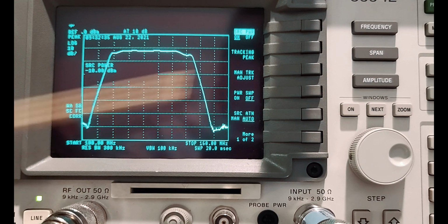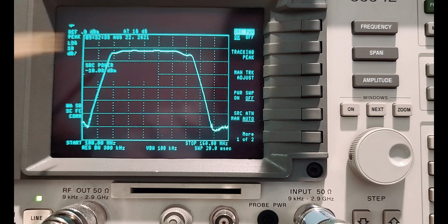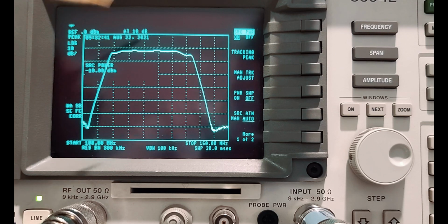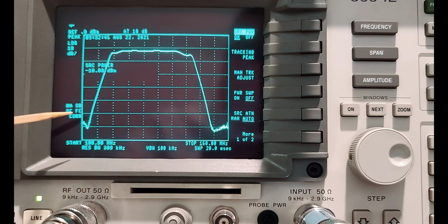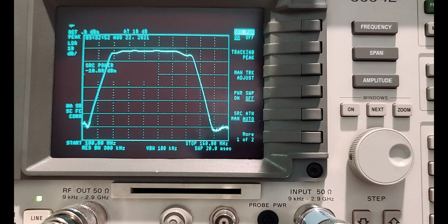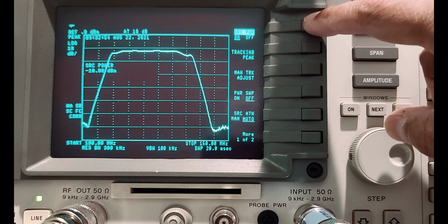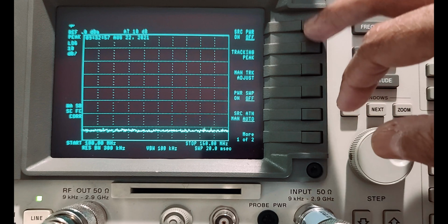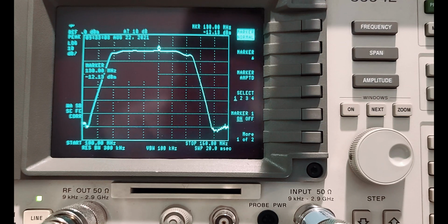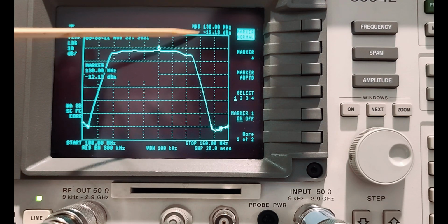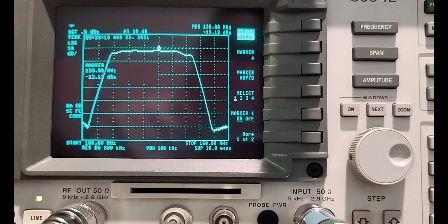Right, so we're not having to deal with the trace or holding the trace or building out a persistent graph for us to build this real-time frequency response. So as you can tell, this is real time. When I turn the tracking generator off, it's gone. Let's turn it back on again. There you go. Now I'm going to go to my marker like we did in our previous example. Go back to marker. Again, we have the same frequency response here. We have 130 megahertz at negative 12.13